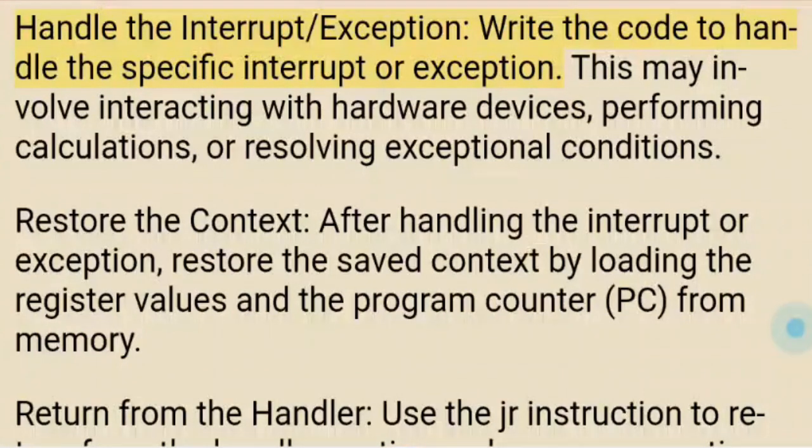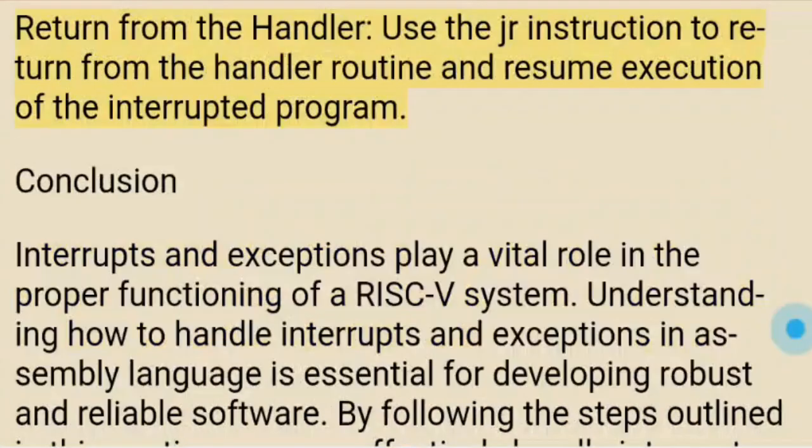Handle the interrupt or exception. Write the code to handle the specific interrupt or exception. This may involve interacting with hardware devices, performing calculations, or resolving exceptional conditions. Restore the context. After handling the interrupt or exception, restore the saved context by loading the register values and the program counter PC from memory. Return from the handler. Use the jump instruction to return from the handler routine and resume execution of the interrupted